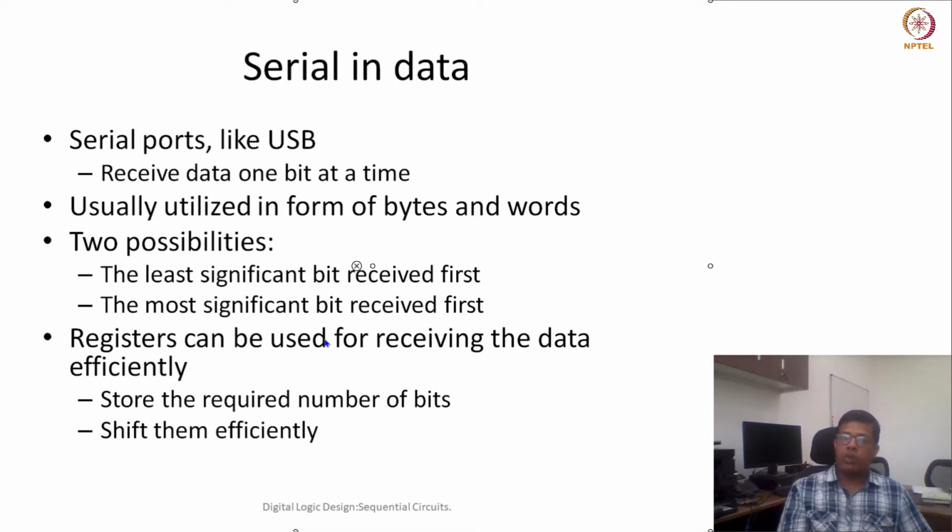Now if you have seen inside the port of this USB, you will see there are only 4 wires. 2 wires are VDD and ground. That's why if you plug in your USB, your phone acts, this USB cable acts like a charger. The other 2 pins are there to transfer 1 bit of data at one time. Although your USB disk or USB drive may contain GBs of data, only 1 bit is transferred at one time.